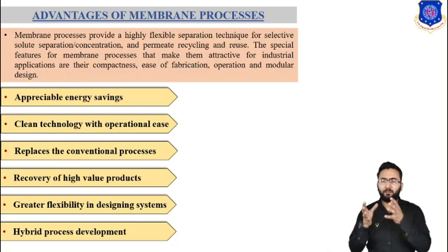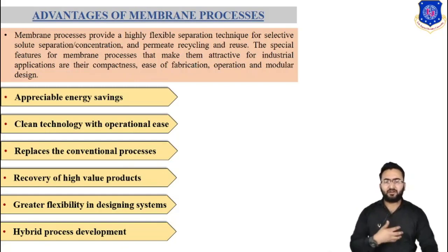The third advantage is that it can replace the conventional process. Existing non-membrane based equilibrium-driven separation processes such as adsorption, absorption, extraction, distillation, and stripping may have significant disadvantages and difficulties such as emulsification, foaming, entrainment, weeping, or lack of flexibility like flooding and loading, the need for a density difference, and other difficulties such as a slower rate, lack of modularity, and need for large space. These problems can be overcome by the membrane separation process.